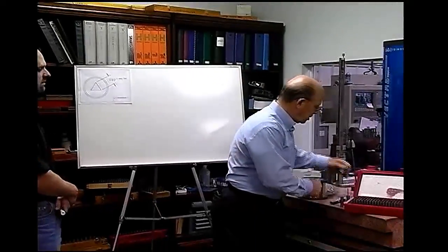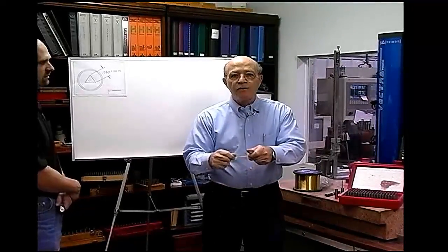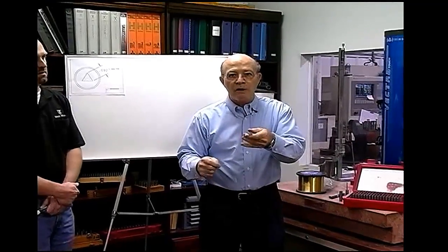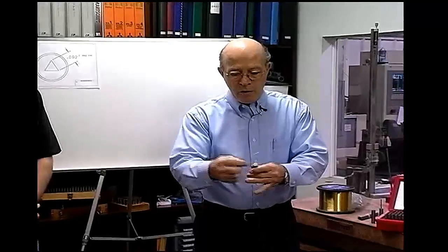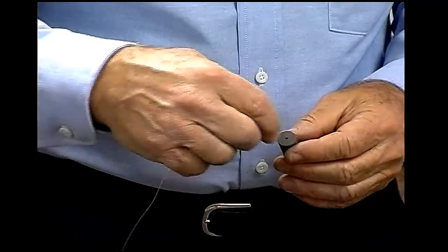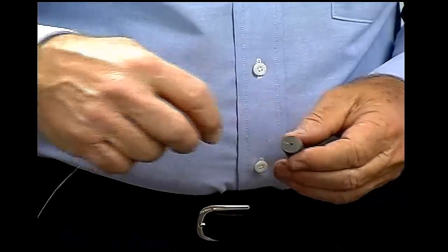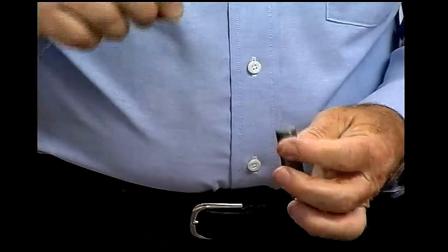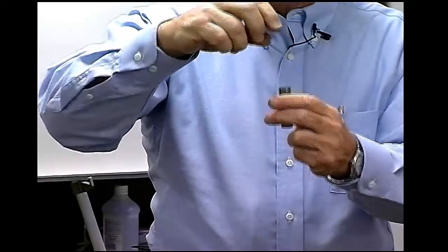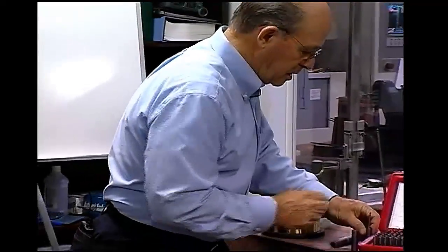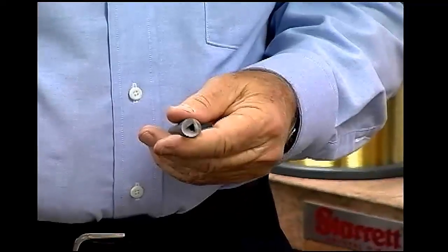And what we do here is, this is a flow nozzle the way we get it, with just a round hole in it. And then we put the wire in here. We thread the wire through, and by means of electrical discharge machining, we cut out the shape, and it comes like this here. This is the shape.